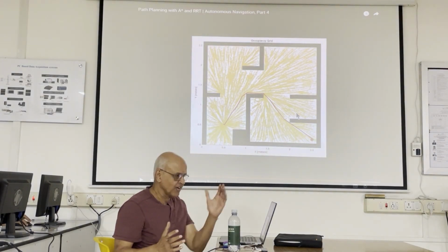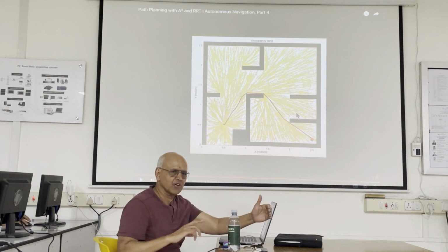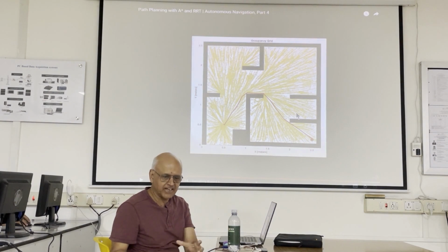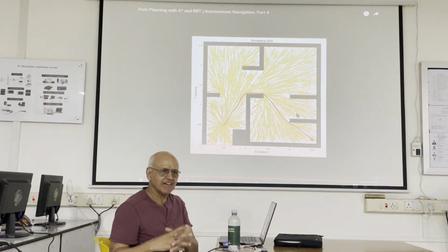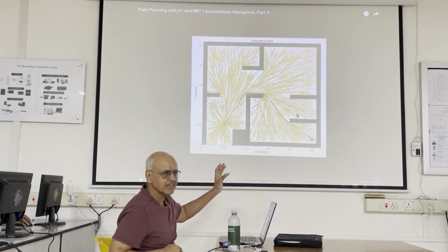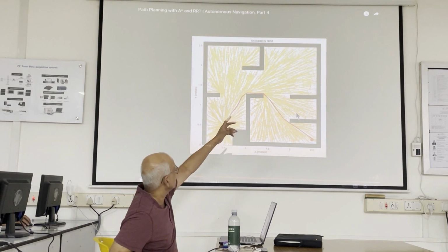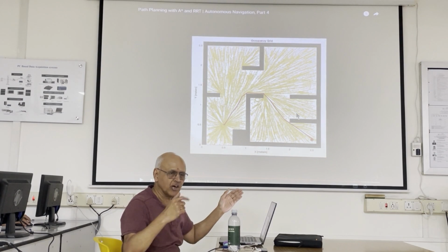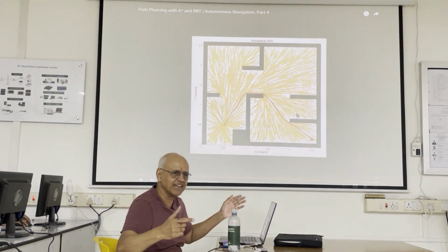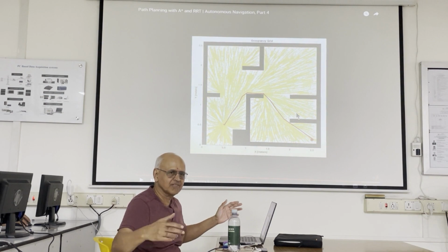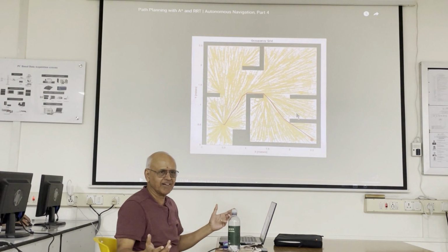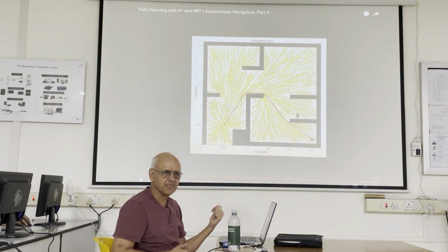We always think of this, okay, this is a perfect path, I've got to get there or else I failed, right? But in practice, you have many other issues in the real world, with the tires on the ground and slippage and so on, bad localization, etc. So at some point, you can stop. And why is it faster? Because the number of nodes explored is still smaller than A star. You got to stop there, because if you're going to go all the way and create like 1,000,000 nodes or infinity, as he says that infinity will give you the perfect path, then you lost the battle, because you might as well have done it through A star.